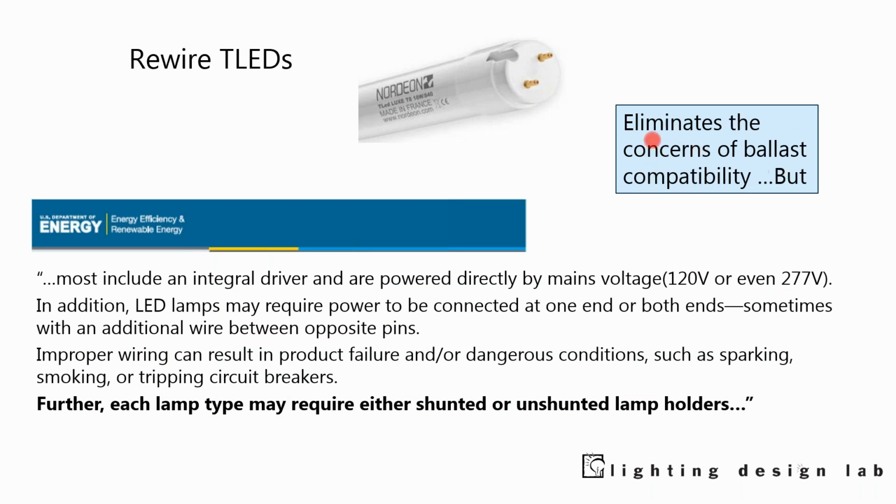Here's the rewire TLEDs. Eliminates the concern about ballast compatibility. That's good, but it must include an integral driver. Improper wiring can result in product failure. Further, each lamp type may require shunted or unshunted lamp holders, shunted or unshunted sockets. So you got to look at those sockets that are on your fixture.